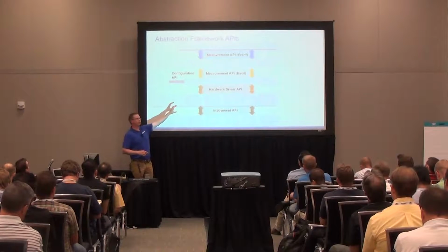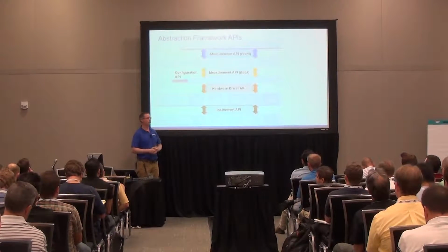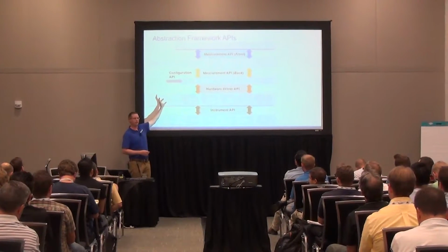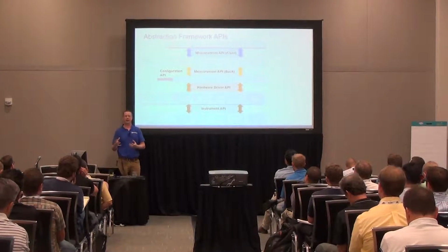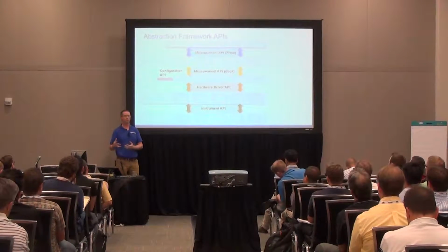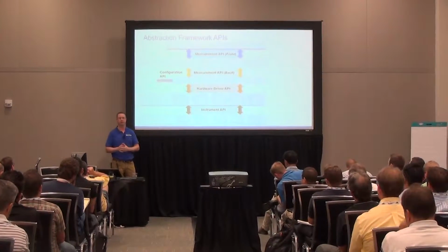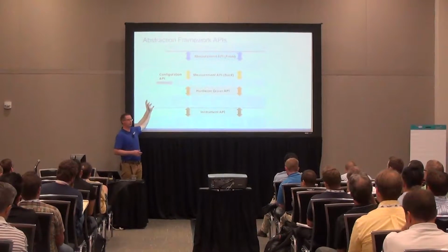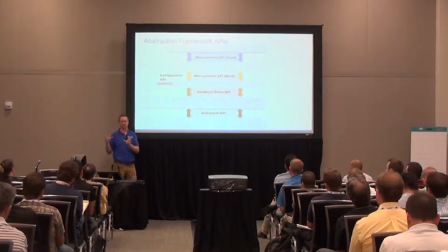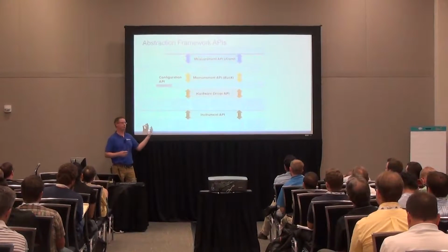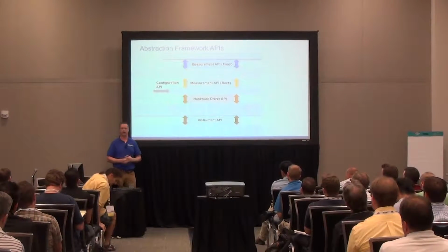So in order for your high-level system, your test sequencer, to communicate with that hardware driver API, you define a configuration API. And that configuration API is essentially controlled by however you want to store your data. At Bloomy, we have something called the UTS software suite, and as part of that, our abstraction framework is called the hardware access framework. And that configuration API for us is really just an Excel file. It stores all the information to convert that alias, that measure 5-volt rail that we talked about at the beginning, into the specific commands that go down to those instruments through that hardware driver API.